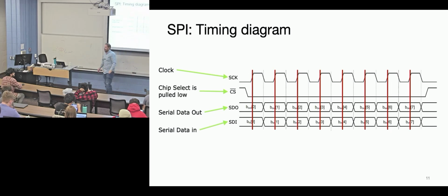Why would you want to change the phase by having it to low? Why would we even want to have these options? Like the phase specifically, you either wait for the second edge or you start capturing on the first edge. Well, it's more about being consistent throughout. It's not that you change it dynamically. It's that you just set it up. Like if I inverted the clock, that would be one of those modes. It would still work. Do you agree with that? And then I could also say, well, I want to sample on the falling edge, but I'd have to move the whole clock half a period over because I don't want to actually sample while I'm during transition. So it's just, yeah, go ahead.